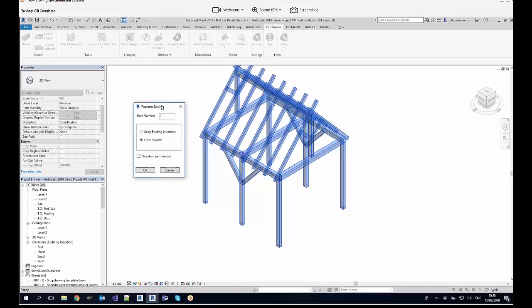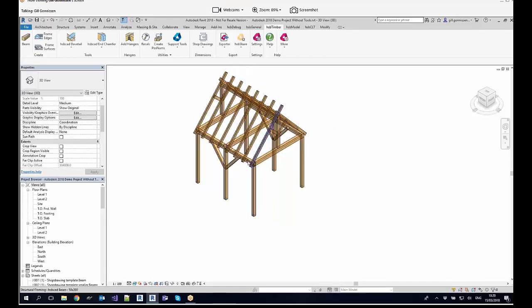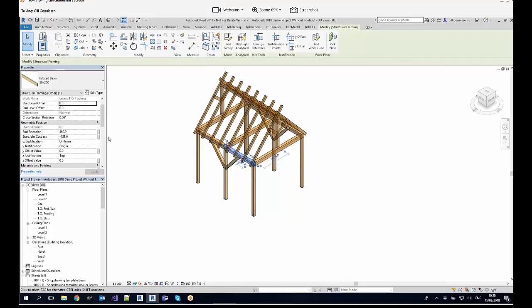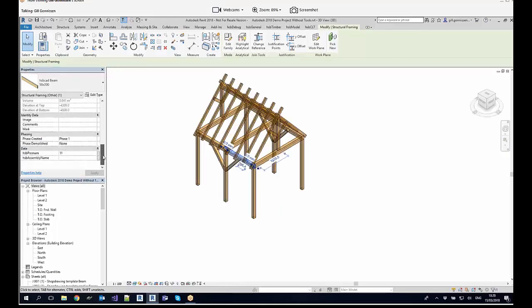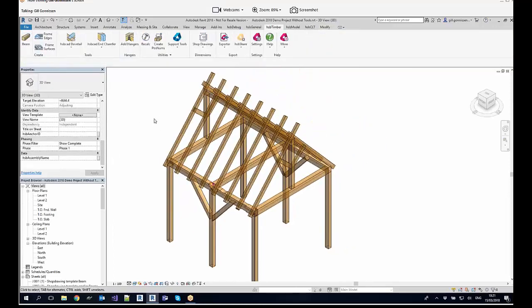If there is a beam that is exactly the same dimension-wise, they will all have the same posnum. So if you click this, each item will have another number, of course. Then it's getting the posnums. As you can see here in the options, this beam received the HSB posnum 11. It's also possible to modify it here, but I wouldn't recommend it because you would get some strange behavior then.